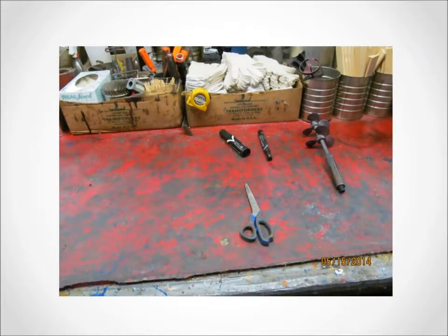Sometimes workers can unknowingly transfer contaminations from their personal protective equipment to other items, such as tools and writing utensils. The benchtop shown here is an area where melted MOCA, isocyanate resins, and other additives are mixed together using the tool on the right. If this surface gets splashed or spilled on during mixing, the contamination could spread to other tools or any writing utensil that the worker will subsequently use.